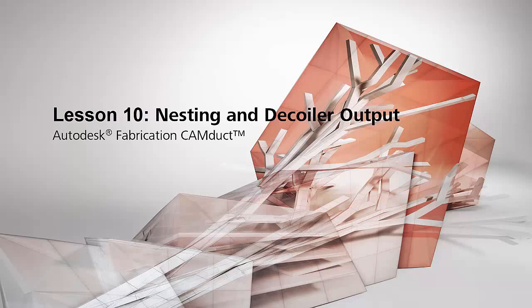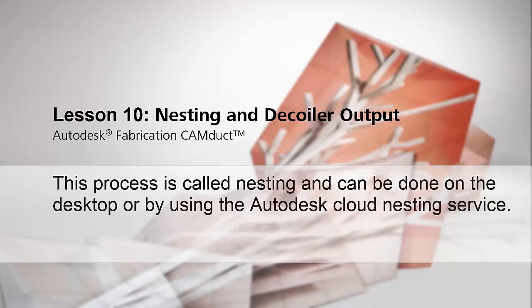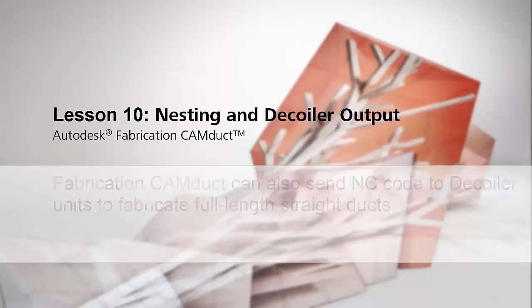Lesson 10, Nesting and Decoiler Output. Autodesk Fabrication CAMduct can arrange the flat patterns to be cut from a piece of sheet material for maximum efficiency and minimal waste. This process is called nesting and can be done on the desktop or by using the Autodesk Cloud Nesting Service. Fabrication CAMduct can also send NC code to decoiler units to fabricate full-length straight ducts.